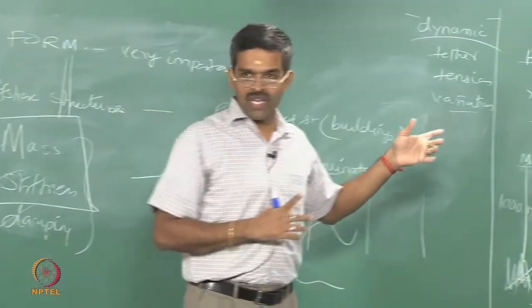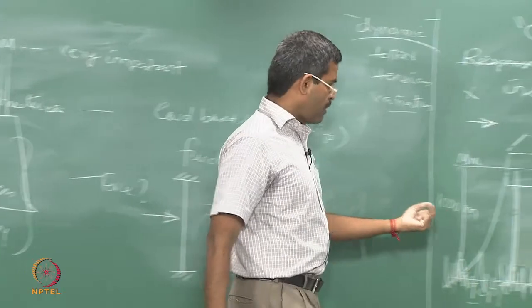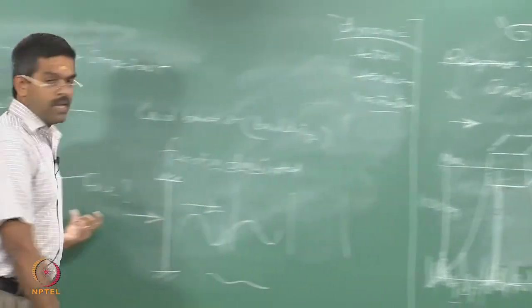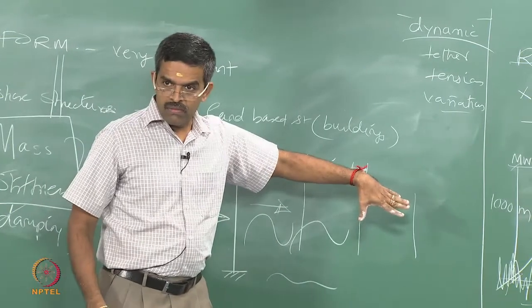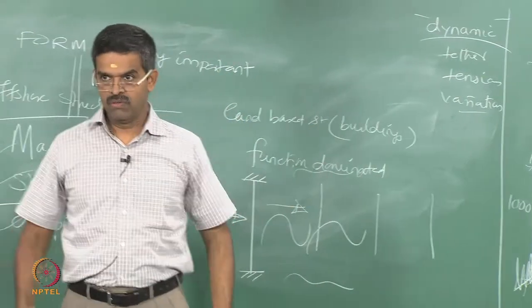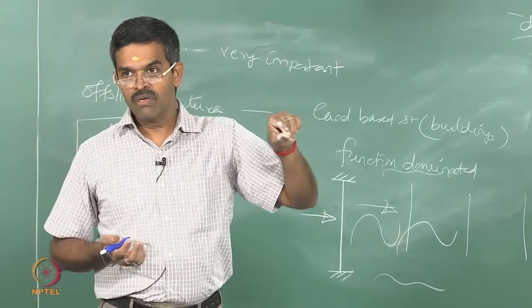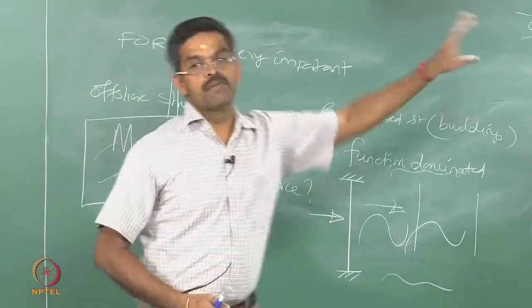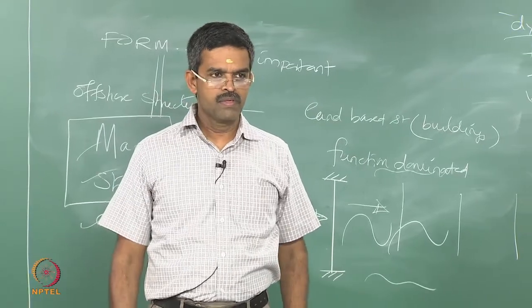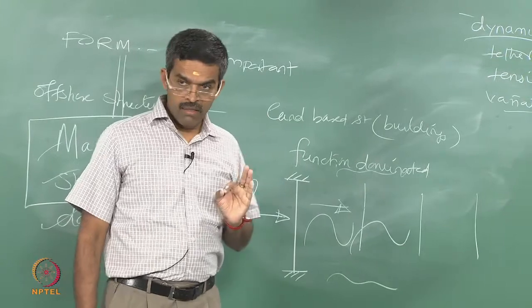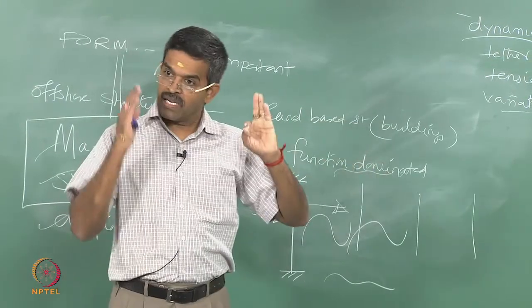So, decommissioning becomes very, very difficult, whereas in platforms like the TLP, remove the tethers, the platform is set afloat like a vessel or a ship. So, drag the vessel using a tugboat, move it from A to B, you have decommissioned it. So, no problem. Decommissioning becomes a challenge, and this was not thought of earlier when people installed platforms in the 1900s.